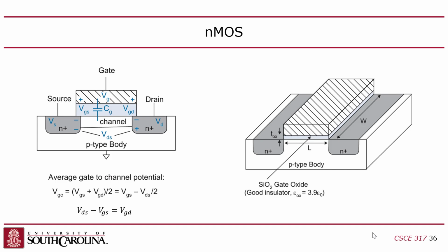Think about this: what is the transistor doing ultimately? It's driving the output of a logic gate, right? It's pulling down to ground or pulling up to VDD. And then that output is connected to the inputs of other gates, and those inputs are connected to gates, right? And gates are capacitors. So why would we want more current into a capacitor?